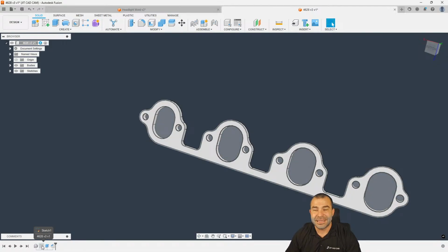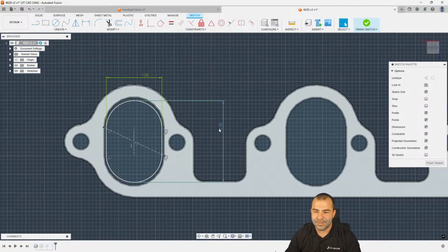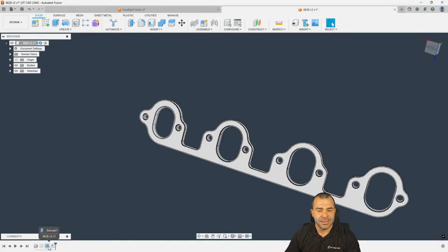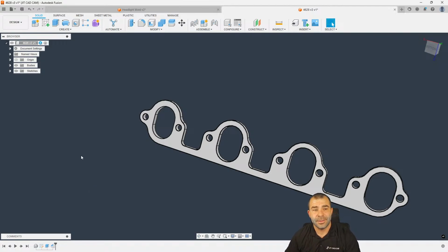I know from time to time, when I've helped him with these drawings, he's asked me, I don't want it to be 2.20. I would actually like to go to 2.21. And that's because that gives that opening just a little bit more room for that tubing that is not precise to be stuck into a precise hole. So again, on our width here, I'm going to go ahead and add an extra 10. And just like that, we've now opened that up. And because of our timeline being linear, everything has come through automatically and adjusted my chamfer on the backside.